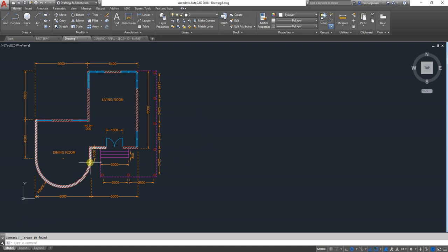When you have an arch in your plan, you can always start from the end or the start point for this arch. So I'll start from this side, which I will select line first, so L, enter, or you can start directly with a polyline. Polyline will give you a continuous line, so polyline, enter, click, I will go up, make sure that the green line is showing, then type 4000.